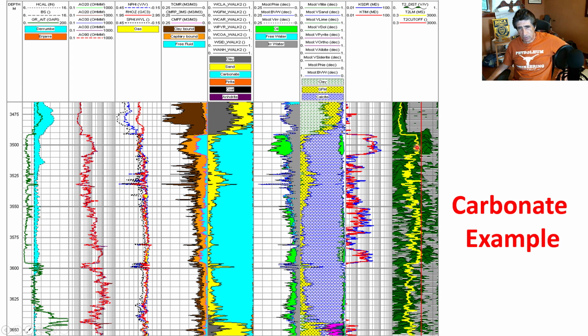And this yellow line is just plotted here as a reference to indicate the location of the median pore size of the distribution. So just by looking at this, we will know that in the upper part the median pore sizes are very small. Here they're relatively high, and maybe smaller at another location. So this is just a different way to present the T2 distributions. And the permeability that you have here was all calculated based on imposing a cutoff between movable and not movable fluids for each one of these samples.